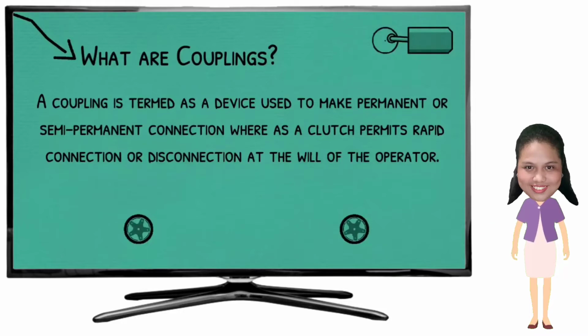A coupling may also be defined as a mechanical device that connects the ends of nearby pieces or objects. Couplings do not generally enable shaft separation during operation. However, torque-limiting couplings can slide or detach when a certain torque limit is exceeded. Coupling selection, installation, and maintenance can result in decreased maintenance time and expense.